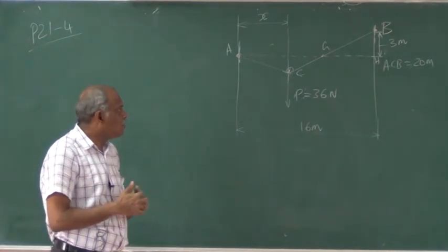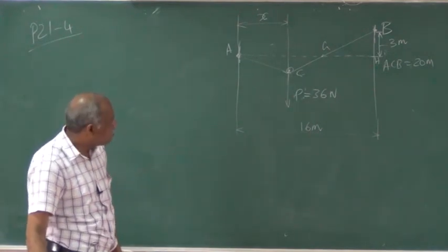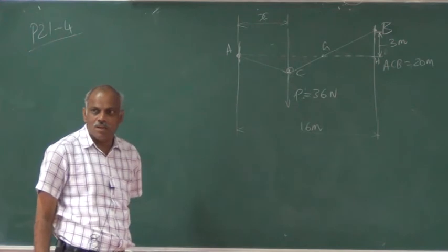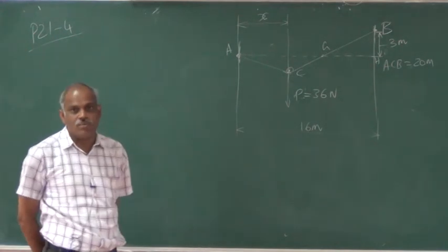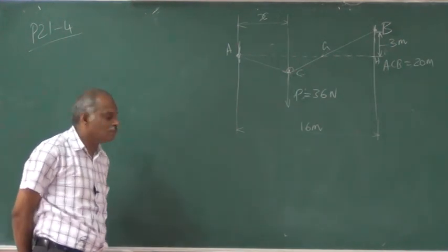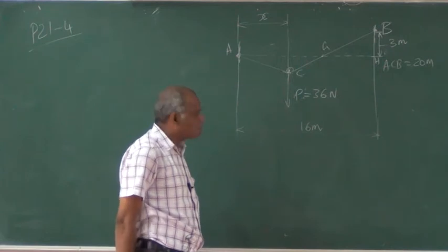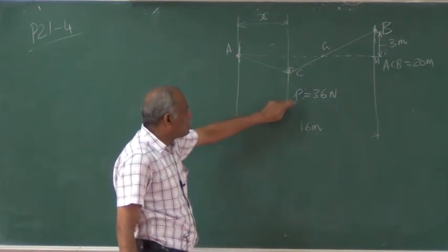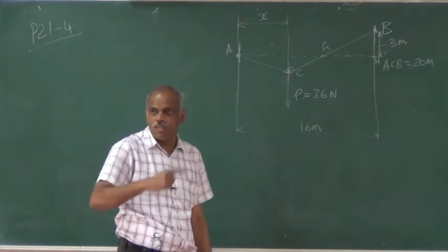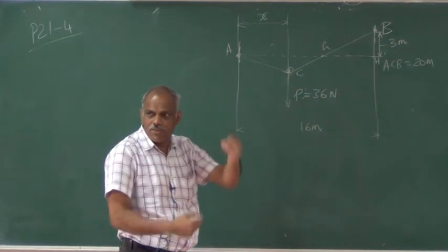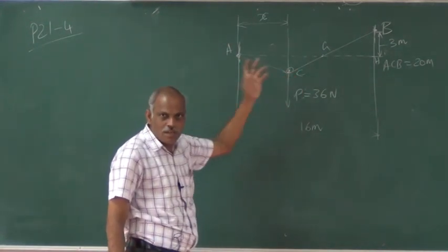When you are looking at the problem and trying to solve it, you cannot move further unless you make some understanding about the nature of the forces that are acting. Now ignoring the pulley radius, we can say that the weight and the tensions in these are concurrent. If the pulley radius is large, it will be difficult. So you can say these are all converging at a point.